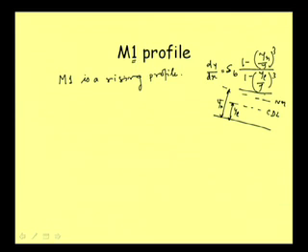So depth at any section is say y, and as such we get that y is greater than yn, that is the normal depth, at any section of the gradually varied flow portion, and yn is greater than yc.